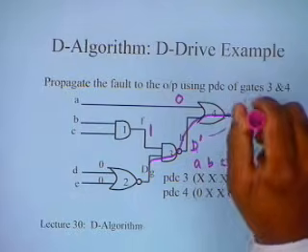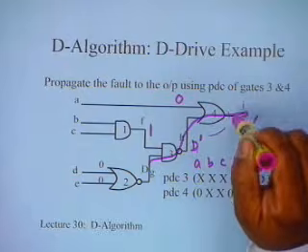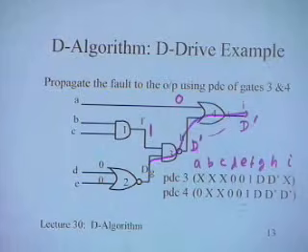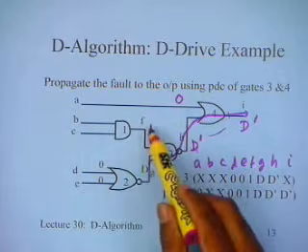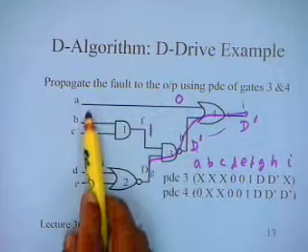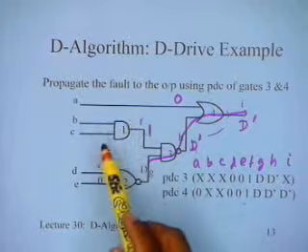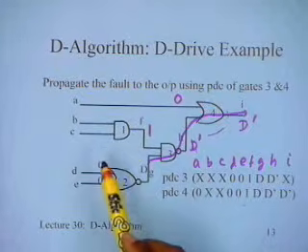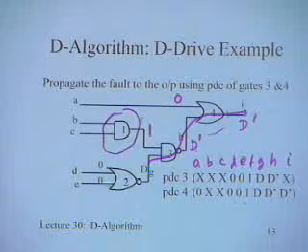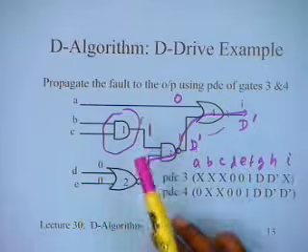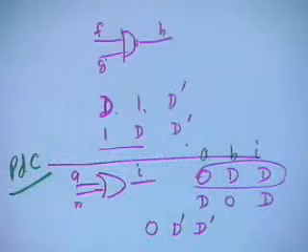Looking at this, if I put a probe over here, looking at this output I will know whether the fault is present or not. But the whole problem is not over, because I still don't have the primary inputs. Of course inputs can be don't care, but I still haven't consistently assigned all the inputs to the gates. This particular gate is still left. I don't know how to generate this 1 for this, and this is the problem of consistency.